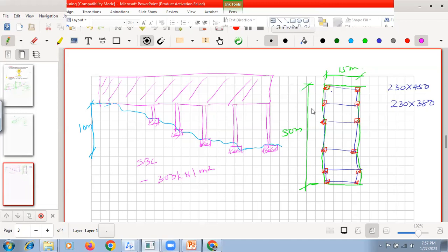This I will call a blunder, because your column sizes are 230 by 380 and 230 by 450, and you are taking 10 meter height. So definitely for slenderness, the column will fail. Here you need ties at different levels, first. Secondly, you need the size of the column to be revised. So this drawing came on site. After that, this was noticed and the drawing was sent back to the consultant, telling him all the situation, and nearly 1 week was wasted because everything was redesigned.